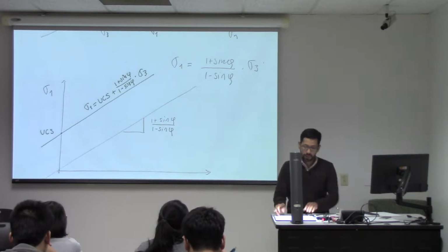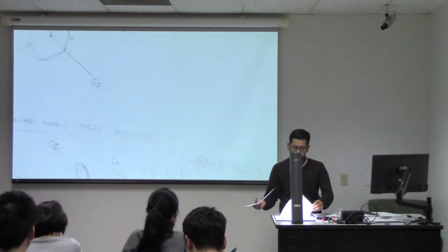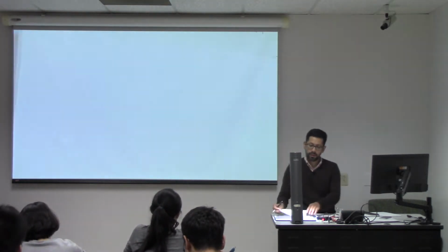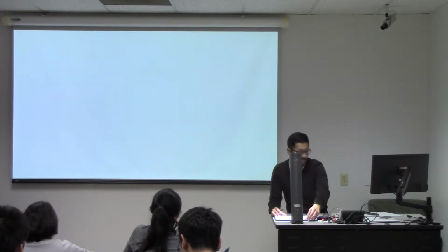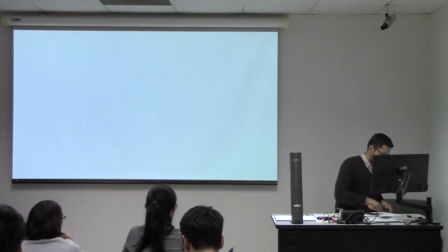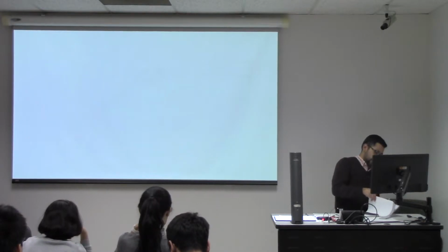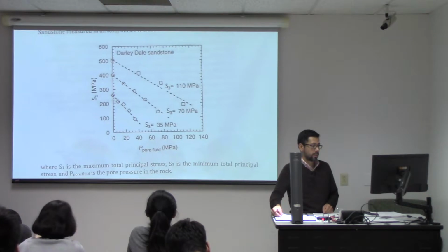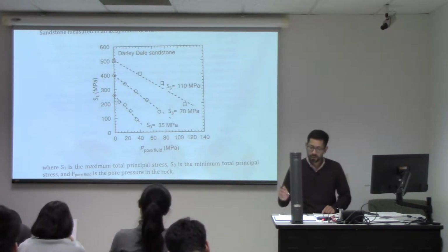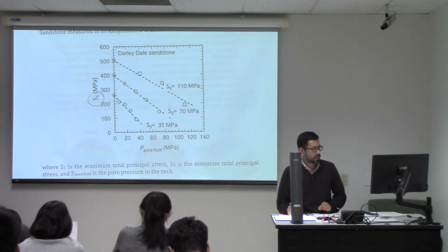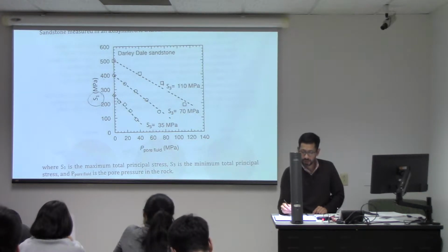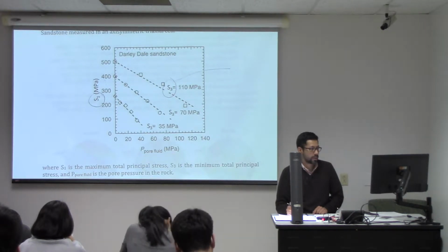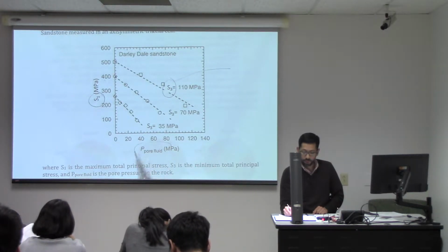So let me explain shortly what a triaxial test is and what you have in there. Basically, in your assignment, in your project, you have data of a triaxial test, where notice you have 3 variables. One, total maximum stress, minimum total stress, and pore pressure.